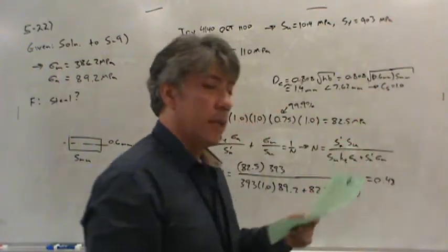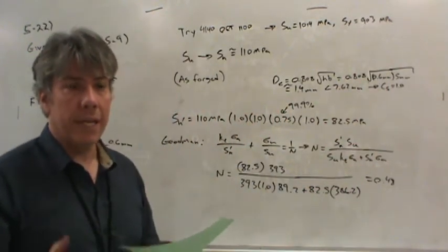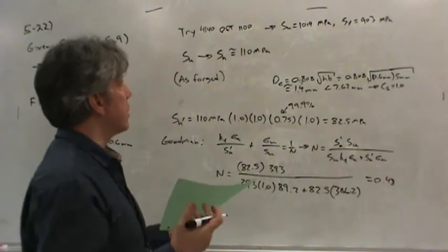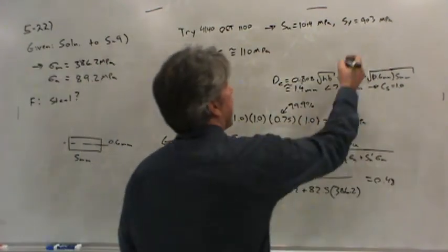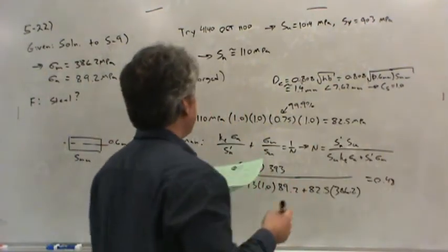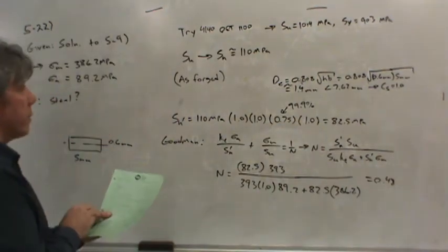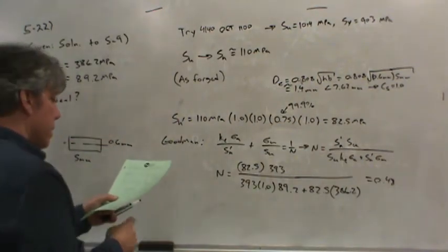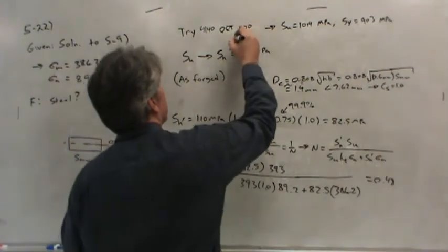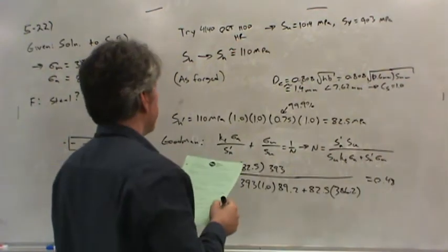And yet its ductility is still 18%, so it can bend quite a bit, which is nice. It's not going to just fracture from bending. So that 18% ductility is what sold me on it, because it's strong but yet still fairly flexible. And by the way, this was a hot rolled steel.